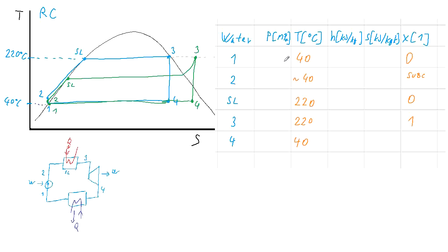So the condensing pressure at 40, which corresponds to 40 degrees C, or if we find in the enthalpy-entropy diagram the point of isotherm 40 degrees C, and it will be at saturated liquid, meaning we would need to go there from saturated vapor, or we can also get the value for saturated vapor.